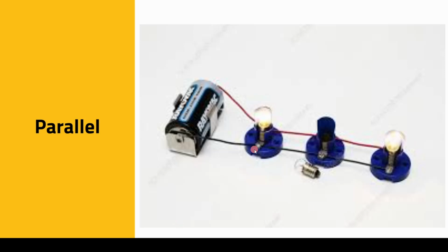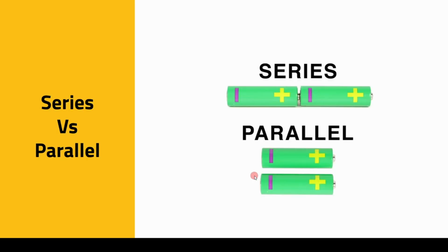So, you have a washing machine and it will have its own switch, so you can control it on and off, and then you will have a food processor, and a dishwasher, and different appliances in your house like a TV and your audio, and they are all receiving the exact same voltage, which is 230 volts. But they have different limbs or circuits or sub-circuits which you can control via switches, and then they draw the current and operate. So, that is a practical explanation or reference to what a parallel circuit is.